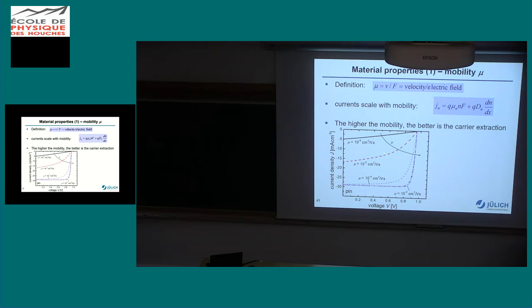And then it goes rapidly down, and then you see, okay, now also I do not collect all the charge carriers from my absorber because they are so slow and they recombine too early, so I'm then also losing in JSC, in the short circuit current. I do not lose in the VOC. Why do I not lose in the VOC?